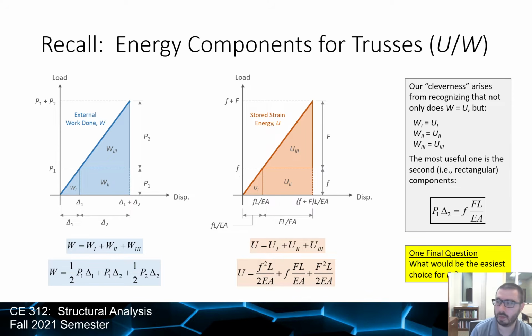If you remember, when we set this up, what we were really after was this term right here, because when we were initially discussing the energy, we found that one of the problems with energy methods was that we could not solve for the displacement at a given joint if there wasn't a load there. So remember, we placed a preload, a fictitious load, a virtual load at the joint of interest so that we could track the energy at the joint that we're interested in.